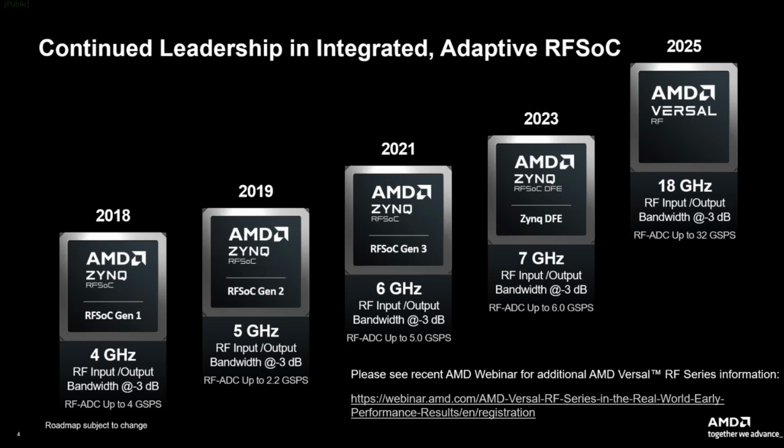This is a wireless specific part. In other words, we actually took the hard IP that customers would normally implement in programmable logic, and we hardened it so that it would reduce the power consumption and the area of the device. So the Zynq UltraScale Plus RFSoC is actually optimized for the wireless market and can support an 8T8R remote radio head with an O-RAN interface, and I'll show you a picture of that.